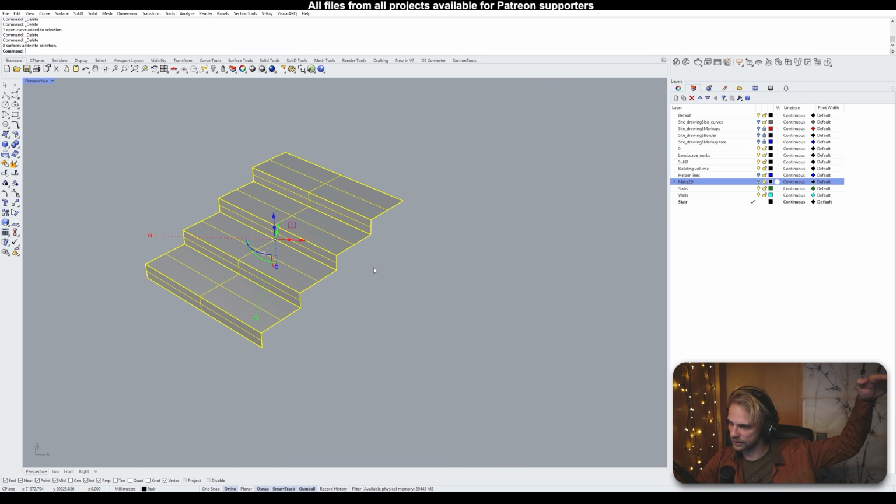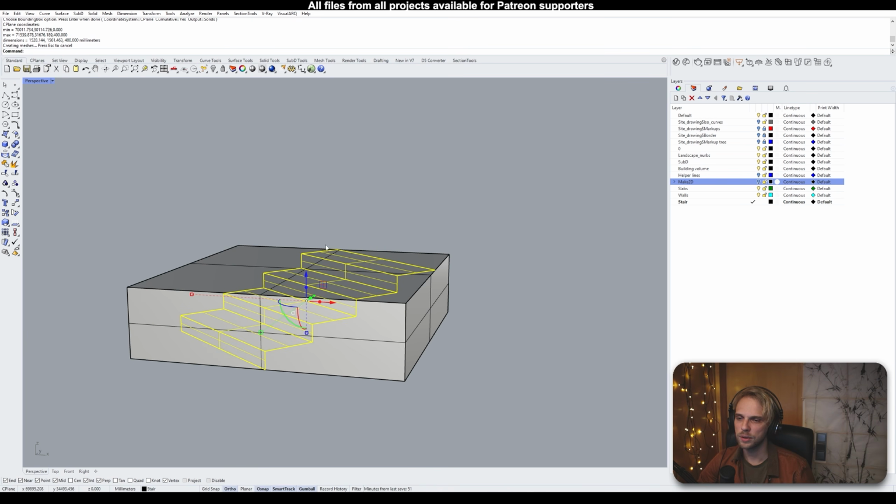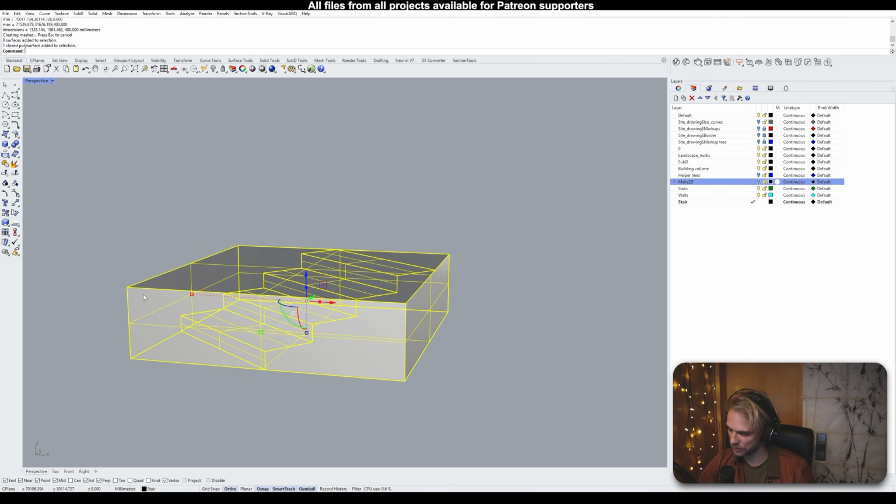Once you have the zigzag done, then you can do a bounding box for the staircase, which basically just gives you a box in which the geometry that you have selected fits. And then you can select the box with shift together with the staircase and scale 1D, scale in one direction, the box together with the staircase from its base point to its top point.